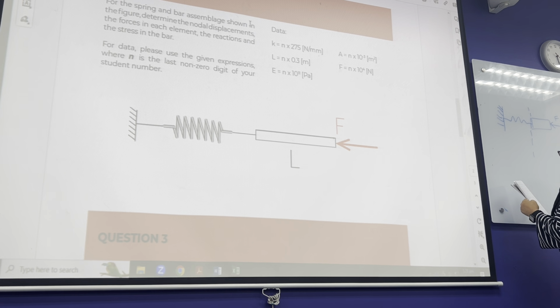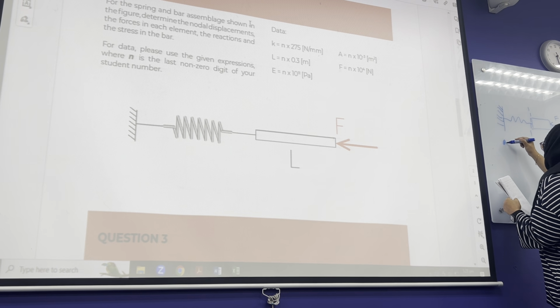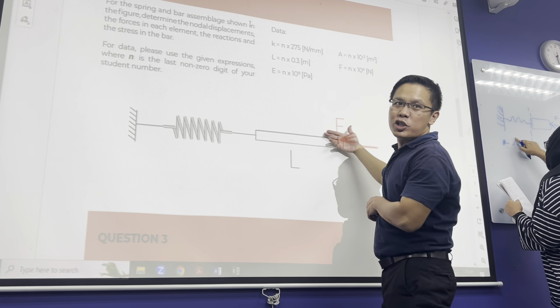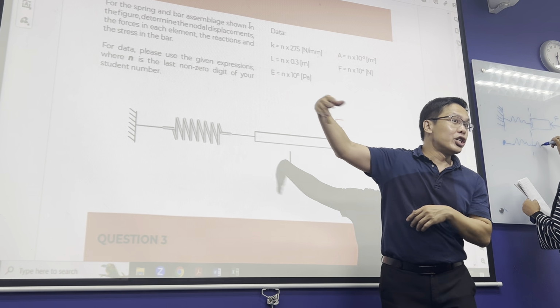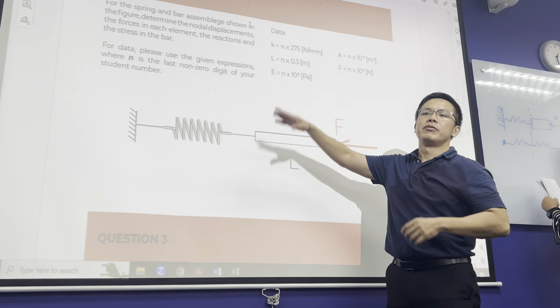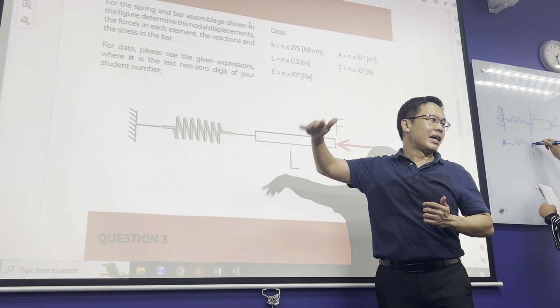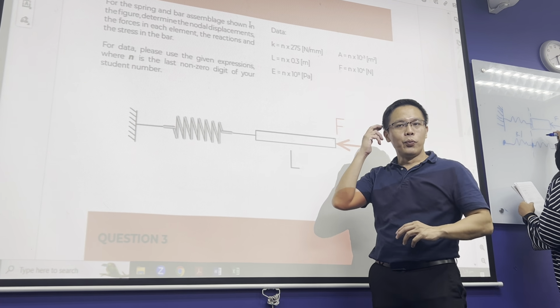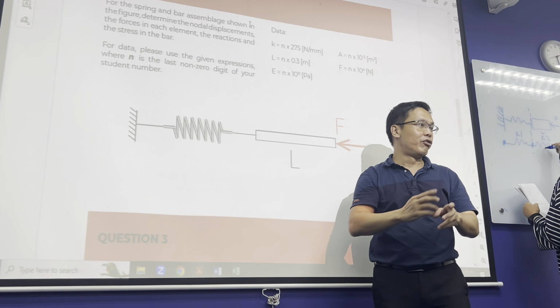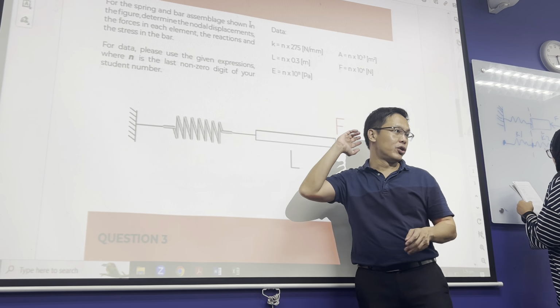Same thing, imagine if this is the actual condition, what do you expect? Imagine you push this right. This will flip up in real life, correct? This one you will see some sort of lateral torsional buckling, that type of thing going on. In this case, no, because we are only applying a single degree of freedom, which is tension or compression, so it will not flip up.